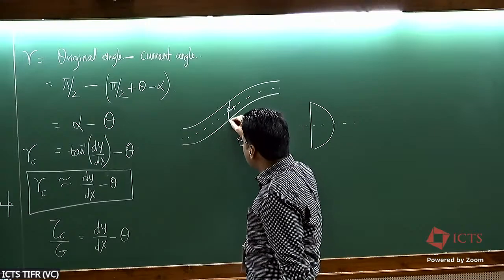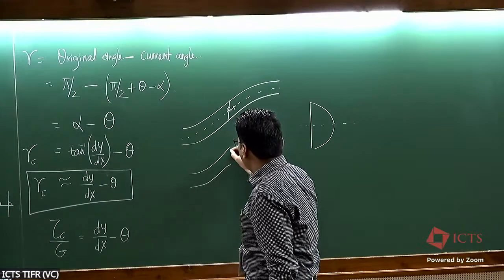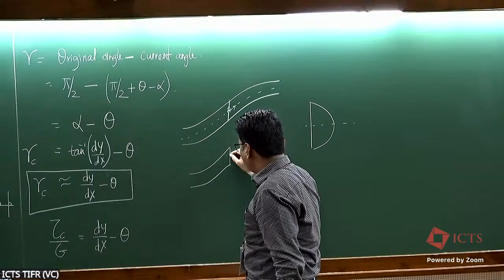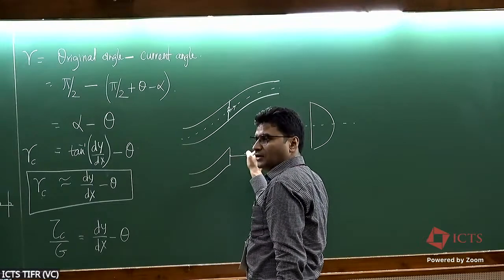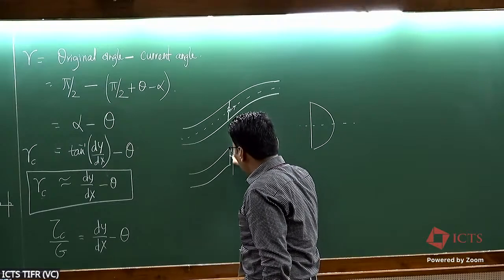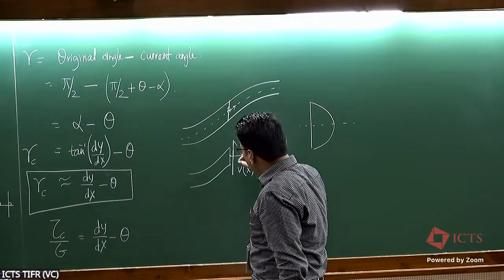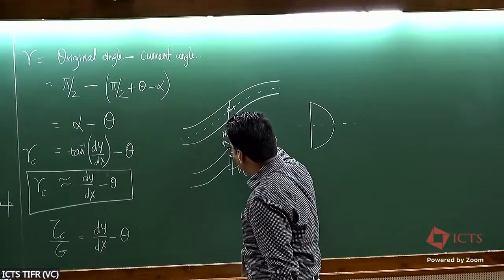If the shear stress here, when you cut it, the total shear force, look at this. Now this is a cross section with positive normal in the positive direction. So shear force will be positive upward. That's V of x. And bending moment here will be anti-clockwise positive, M of x.